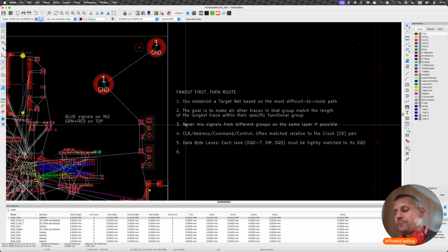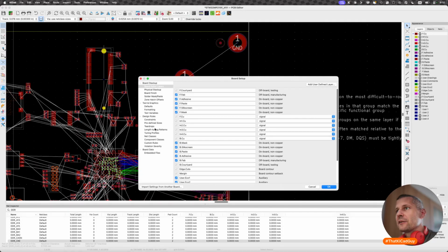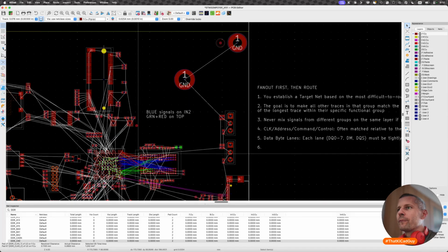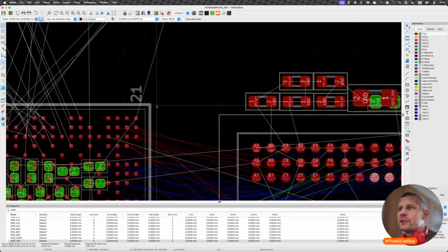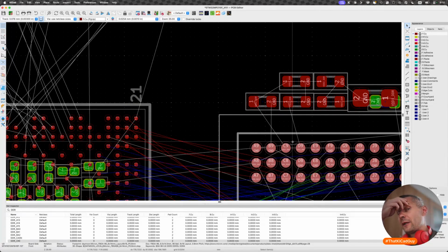Another thing is that when we check the net classes from the last time, we have a BGA fanout, which is the net class for all the signals that need to be fanned out from the BGA of the MPU, which is a fine pitch BGA. The DDR is, let's say, a normal pitch BGA.